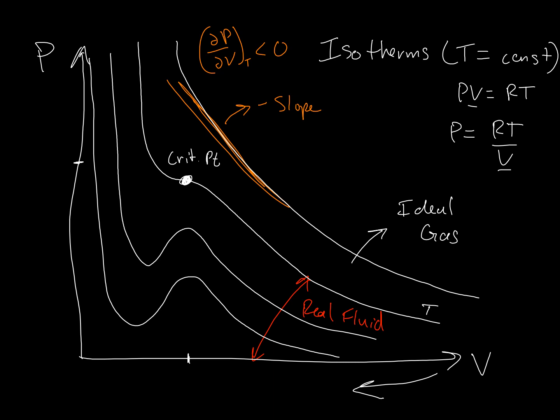So in a cubic equation of state, there are regions that are unstable. We violate the stability criteria. That region is right there. We'll talk a little more about this when we get more in depth into the theory of phase transitions, but this is actually called the spinodal region.